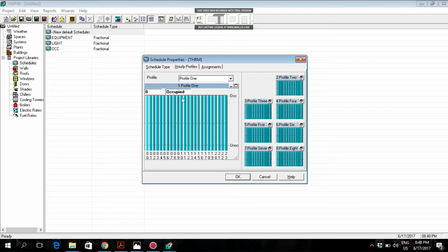If you do further cooling, the temperature will drop from 20 degrees to below. In the same way, if the temperature rises to 24 degrees, which is the maximum set point, the machine will be on. Or you can set one set point only, 20 degrees centigrade, without any window, without any gap.